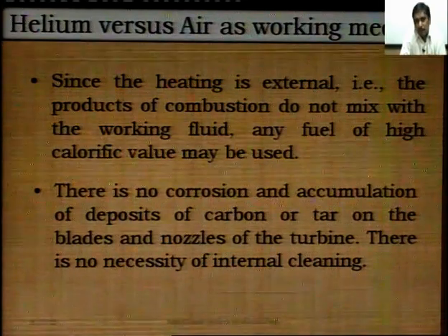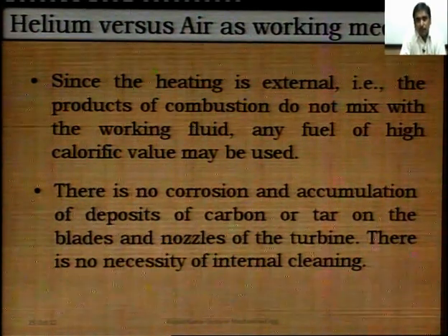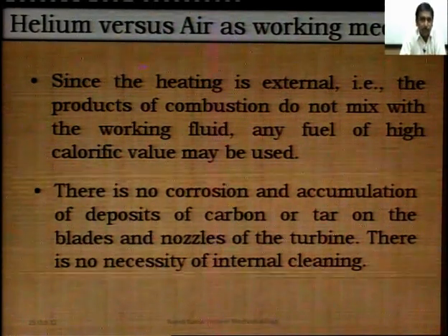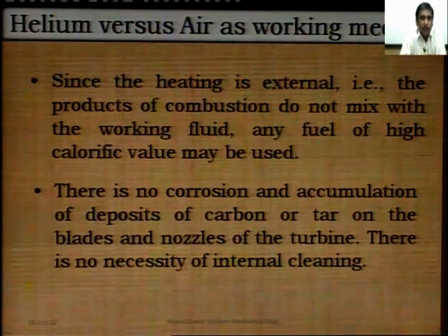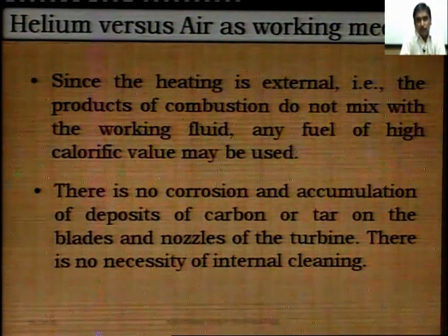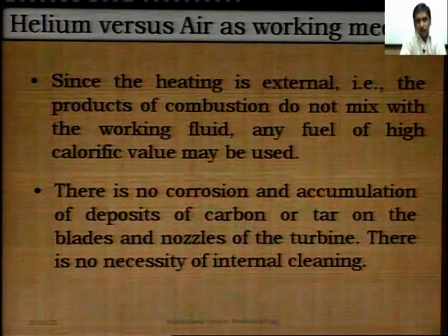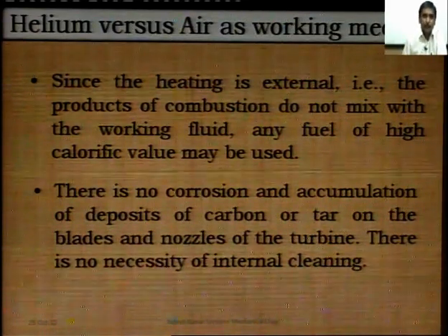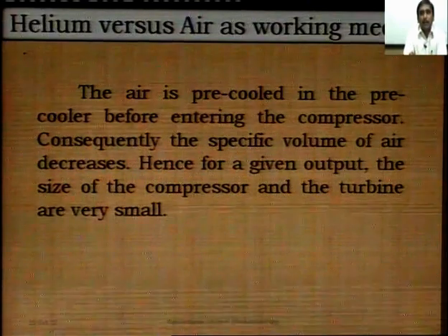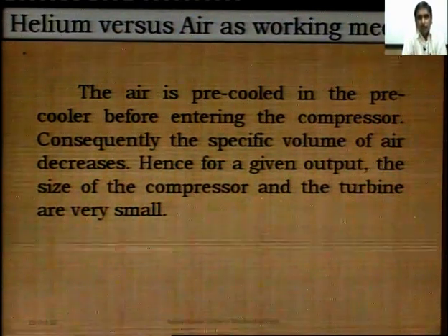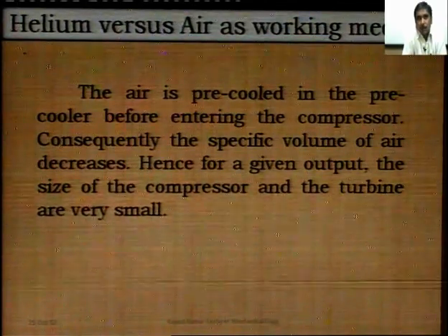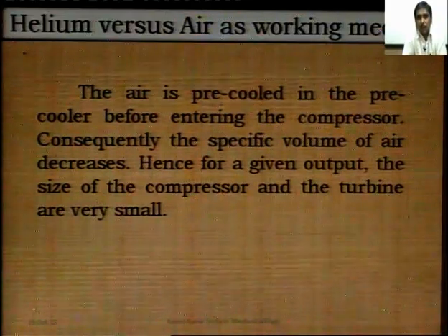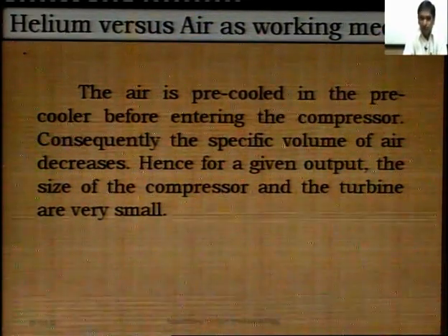Since the heating is external, the products of combustion do not mix with the working fluid. Any fuel of high calorific value may be used. There is no corrosion and accumulation of deposit of carbon or tar on the blades and nozzles of the turbine. There is no necessity of internal cleaning. The air is pre-cooled in the pre-cooler before entering the compressor. Consequently, the specific volume of air decreases. Hence, for a given output, the size of compressor and turbines are very small.